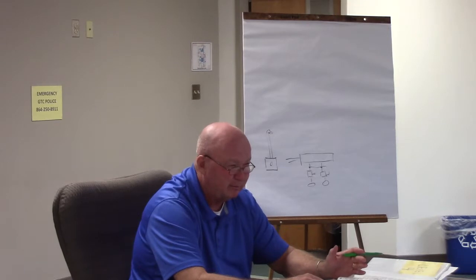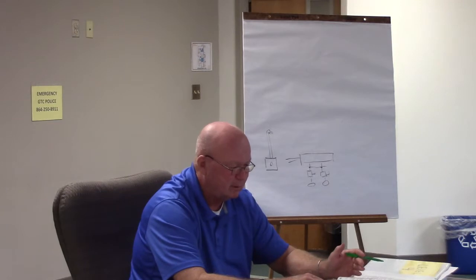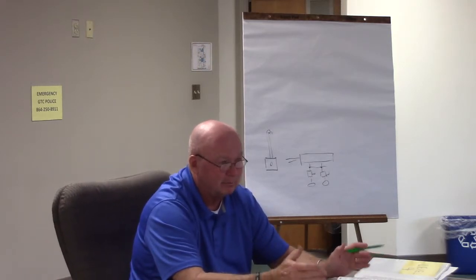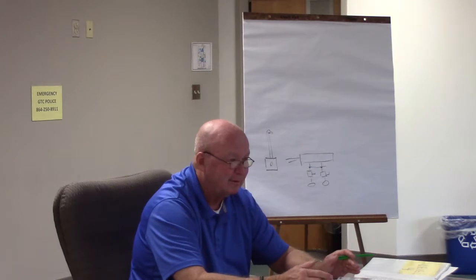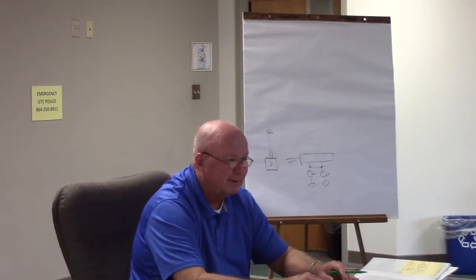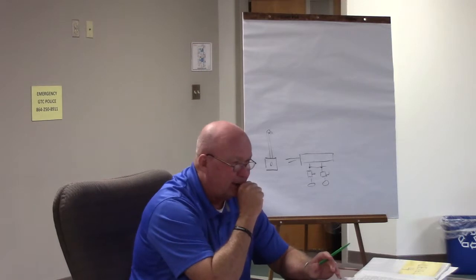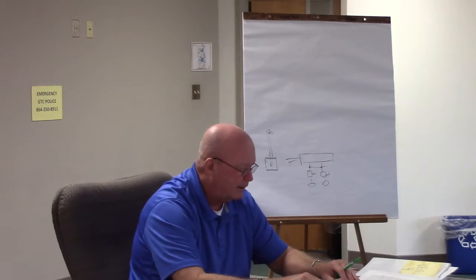Most of the time it's not something y'all do in the field. I mean, it's something that's calculated for you before you get there. But it doesn't hurt to know, in case something looks out of order. Or you may be wondering, why am I pulling a number 8 wire to this receptacle? Now, common sense says you're not going to hook up that number 8 wire to that receptacle, right? I hope not. What are you going to do? Put a little pigtail on it. Yeah, you're going to put your pigtail on there. But that receptacle isn't going to take that number 8 wire, right? Good. So we know that. All right. Number 17.